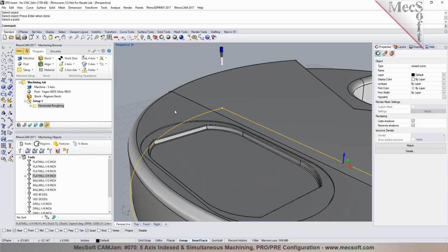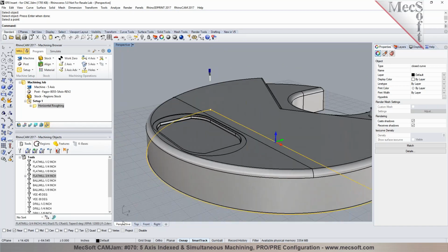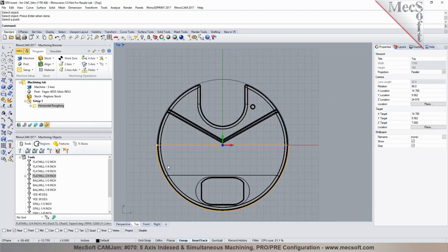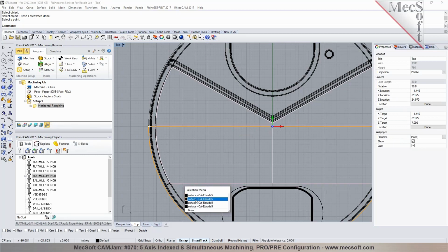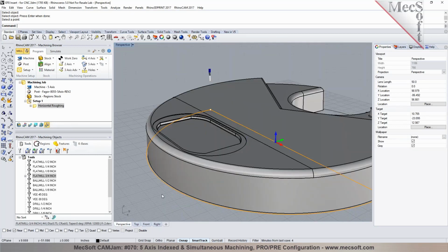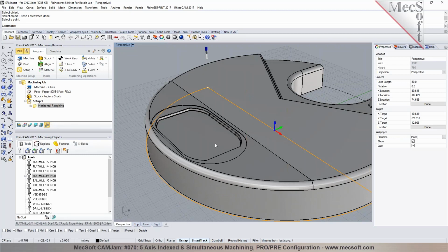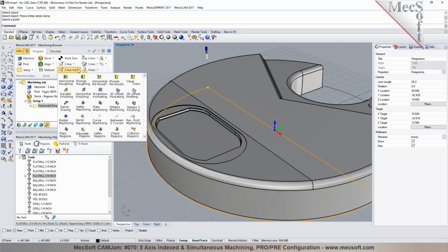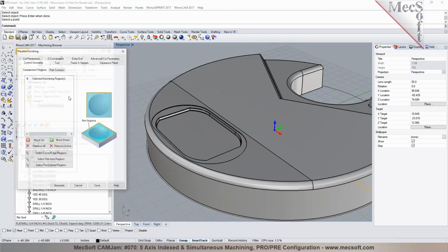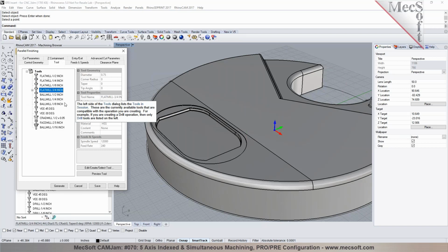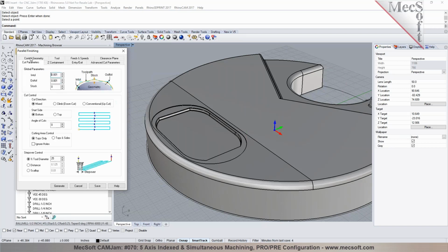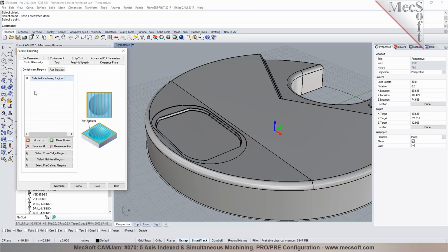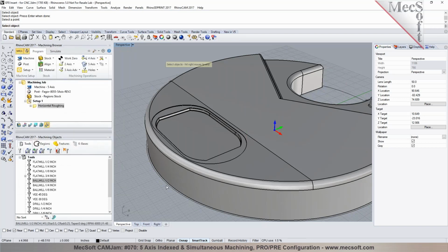If I want to go back and do a finishing pass to a certain area only on the surface in here, I can actually select the surface and apply a toolpath, or I can just do a 3-axis toolpath in here. For the surface, I can use 3-axis and start with a method like a parallel finishing operation. I can pick a tool. In this particular case, I could be selecting a ball end mill, specify feeds and speeds, set the cutting parameters, set the step overs in here, and again I can pick a boundary to contain it, and I can pick this boundary right there.